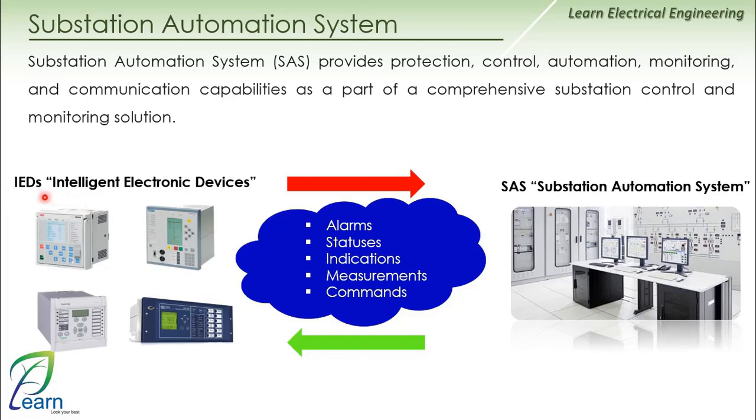Now you have the IEDs, a collection of relays. I have something like the protection relay protecting the switchgear panel or the switchgear feeder. How about using it in control as a BCPU, the bay control and protection unit? For GIS, install it for GIS. If you use it with bay control, I call it the control unit, which is a unit that controls the cells you have. Great, okay, so now, what is the status of my IED or my relay? The idea is quite simple.